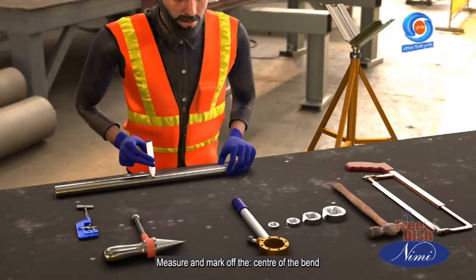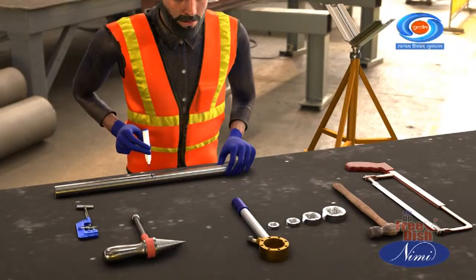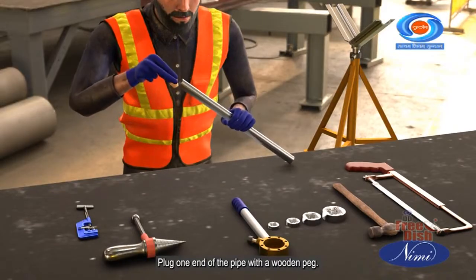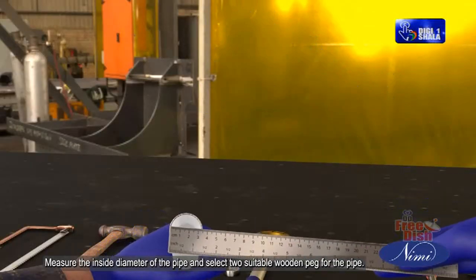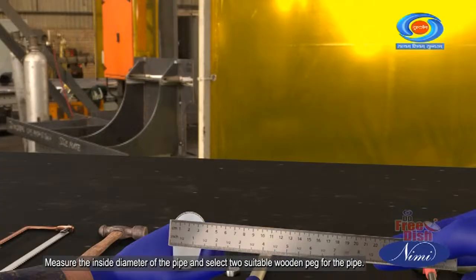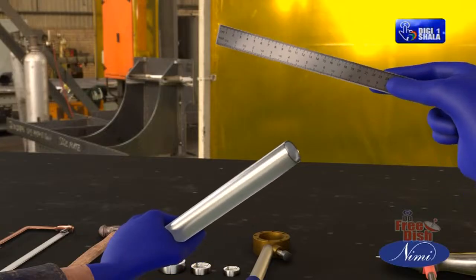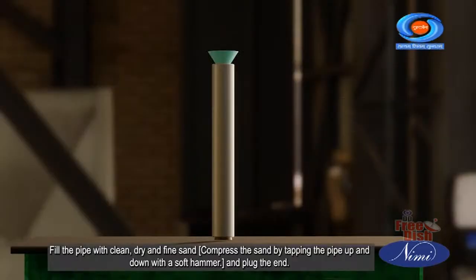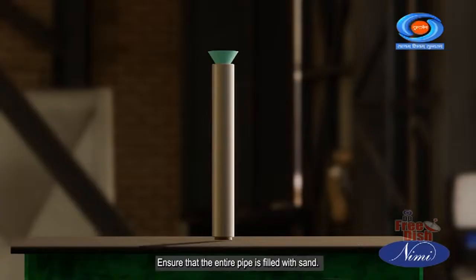Measure and mark off the center of the bend, beginning and end of the bend from the center line. Plug one end of the pipe with a wooden peg. Measure the inside diameter of the pipe and select two suitable wooden pegs for the pipe. Fill the pipe with clean, dry and fine sand. Compress the sand by tapping the pipe up and down with a soft hammer and plug the end. Ensure that the entire pipe is filled with sand.